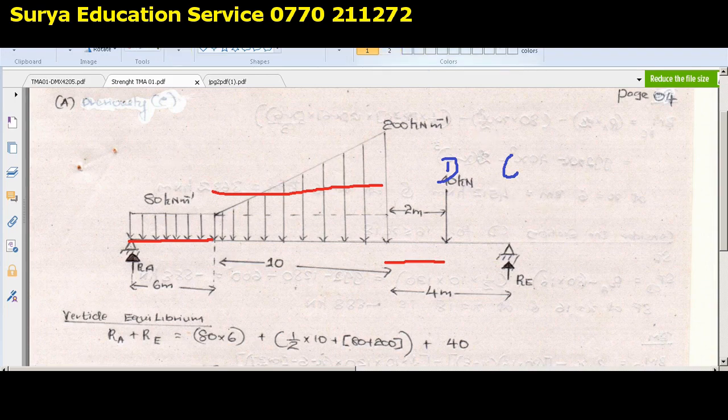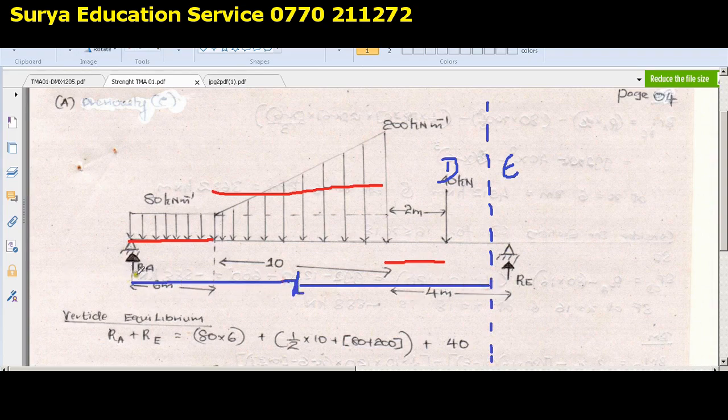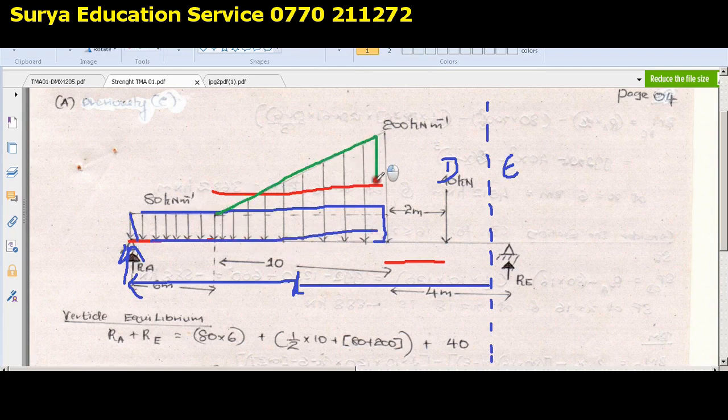I think I will sketch the section. So now this is our section, right? Okay, that means we are going to break the beam here, some little distance away from the end. So the x distance, I can say it is the x distance measured from this extreme left end up to this section. Yeah, so now you know it's very easy. We have positive shear here, right, because left side is going up. Then this rectangular thing, and then we have this triangular one.